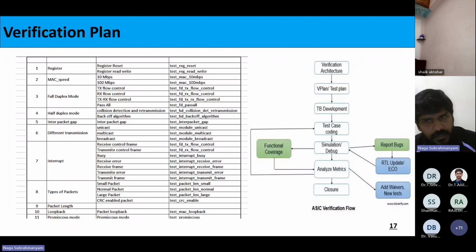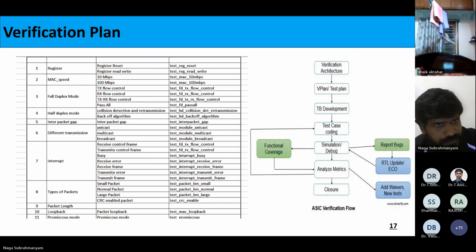Ethernet has a list of registers, around 21 registers, and they have one control thing. You all know what the control thing is, right? It's a state machine. So now in my verification environment, I'll try to write one value into the register. That's called register configuration. Based on that value in the register, the state machine will move. So try to imagine the thing.